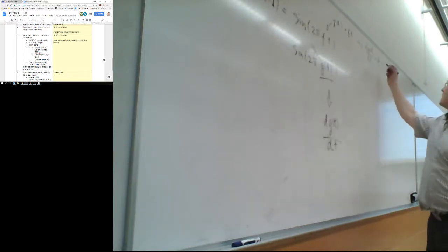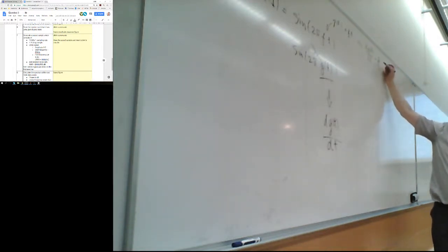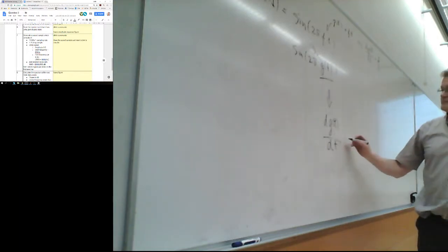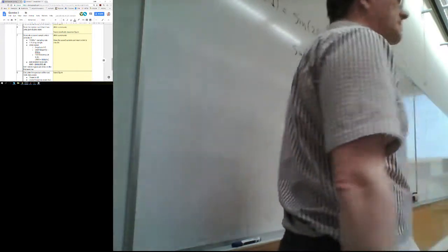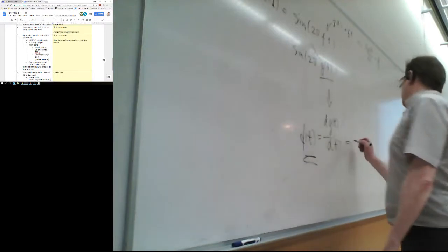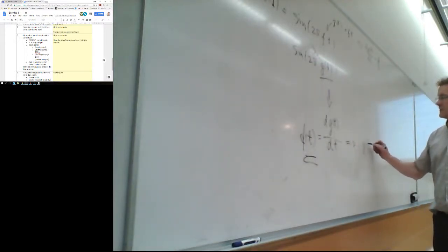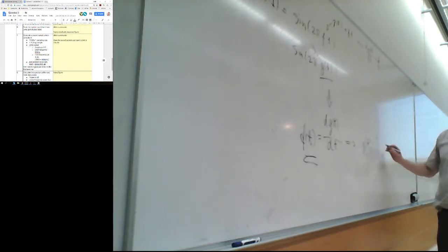So basically, if you want to generate a signal with the varying frequency, you need to plug in on this sine 2 pi ft an integral of that.